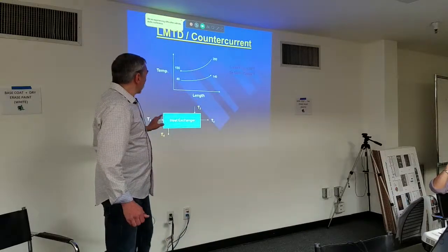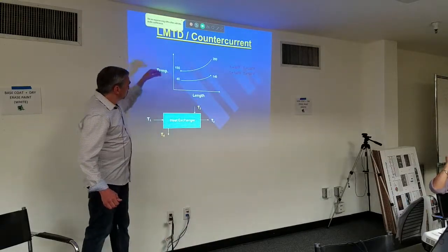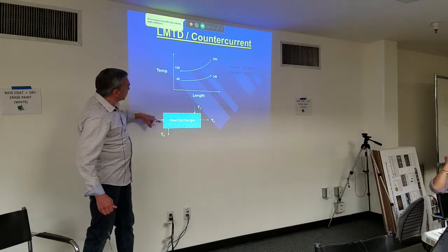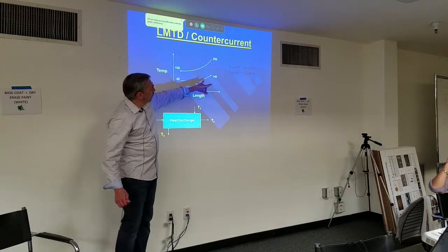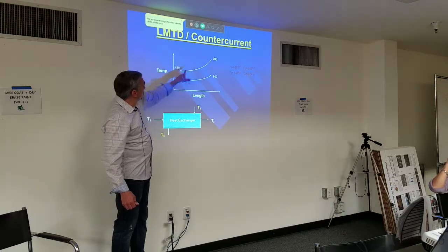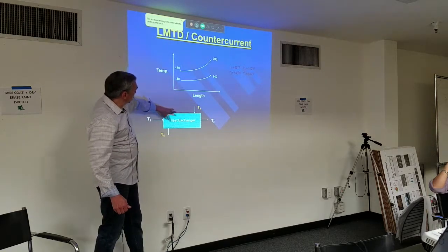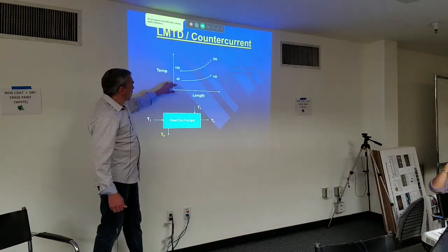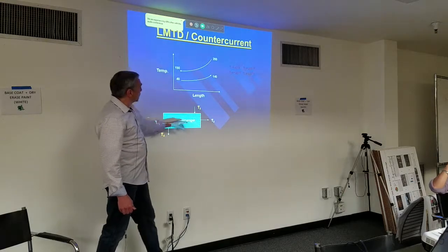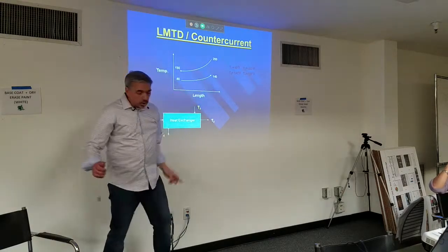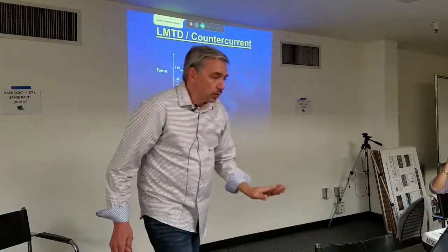One. Now notice that this is a counter current heat exchanger, right? So we're going to plug in some values. We'll just plug in 200 to 150. So our entering water is 200 degrees coming across here and coming out at 150 degrees. This fluid is entering at 40 and coming out at 140. We plug those numbers into our formula.